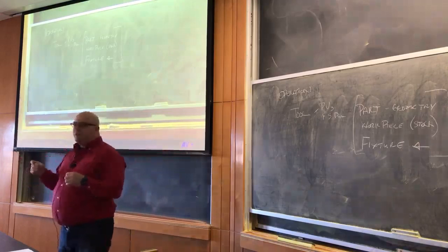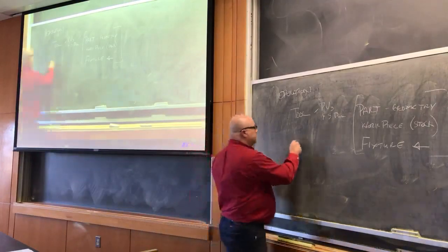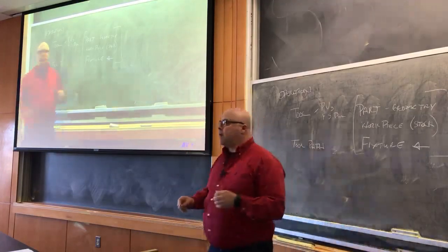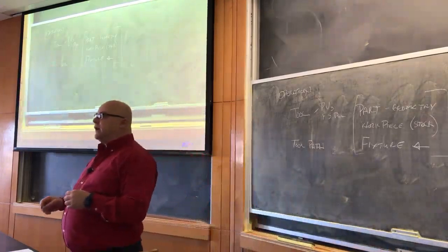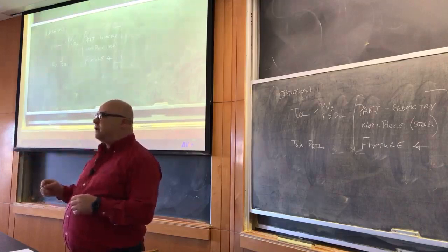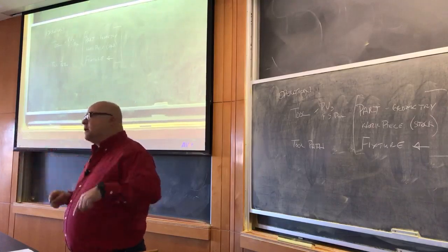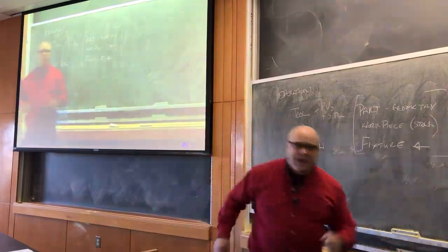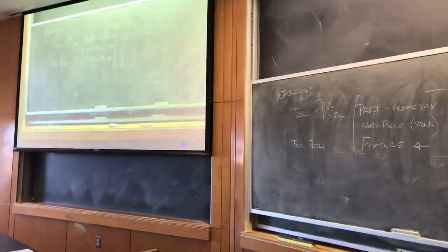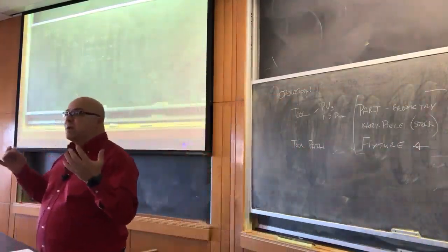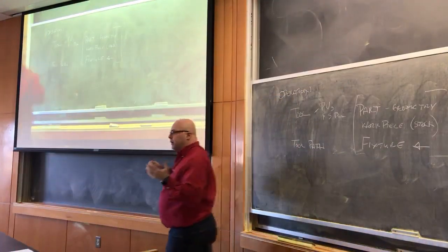Yep. We've got to create the tool path. And so it's entirely possible for us to sit down there, and if we know that G01 makes the tool go in a straight line, and if we know that G02 makes it go in a clockwise arc, and G03 makes it go in a counterclockwise arc, and that G00 makes it move as fast as it can to the spot we told it to go to, then we could sit there with a piece of paper, and we've got a drawing for our part, right? We've got the art. We know the shape of the part.